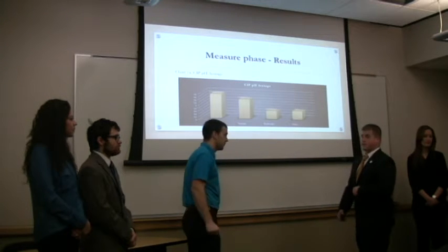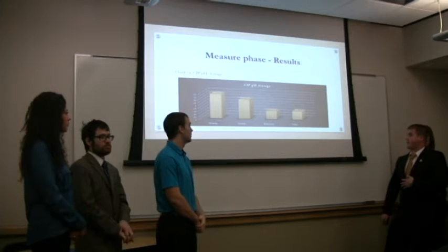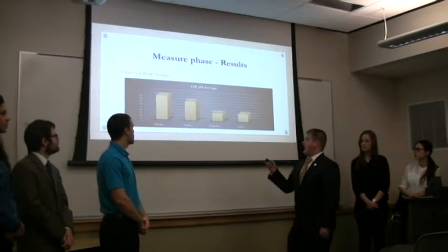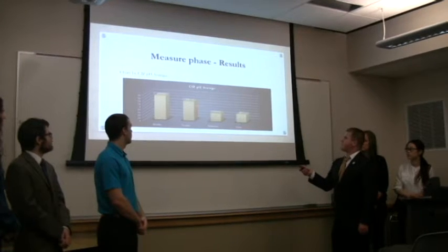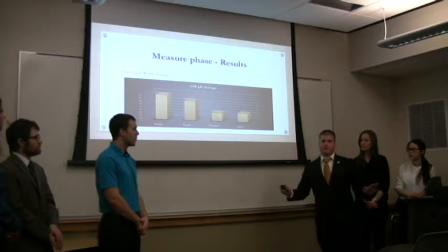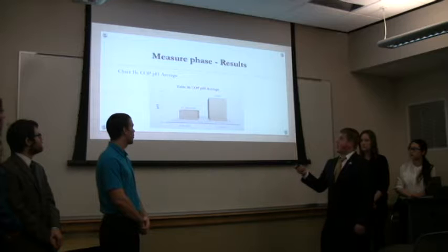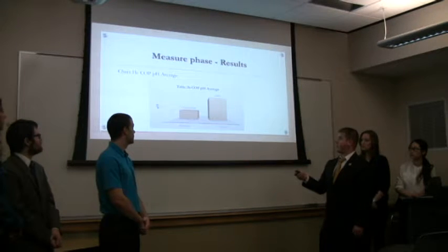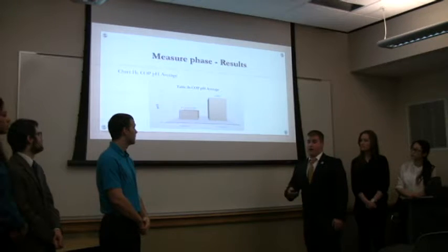All right, this is basically an overview of the information we got from our measure phase. This is a graph of all the main averages for each given day that we have. As you can see, we're sitting a little bit either below 9 or above 9 as an average between all of the pH samples. And that was for our CIP. For our COP, we didn't get as many measurements during the measure phase, but we still got Monday and Tuesday measurements, and they're all, once again, hitting right about 9 as a total average.